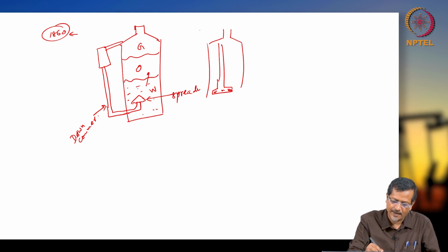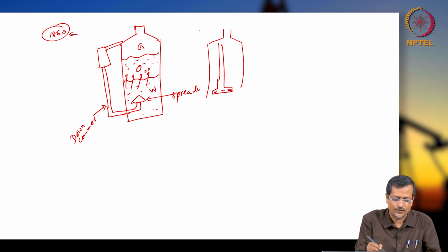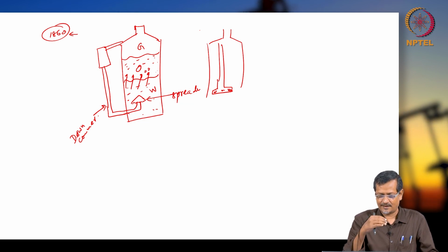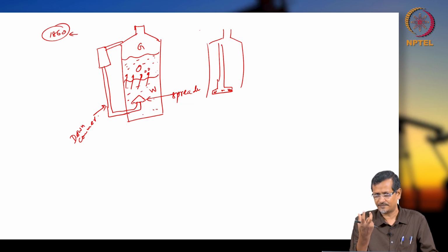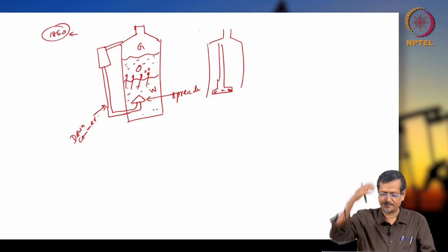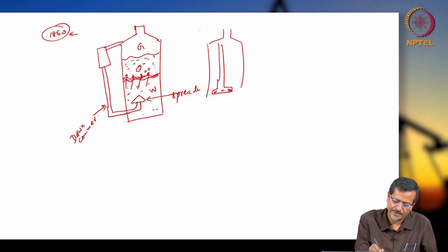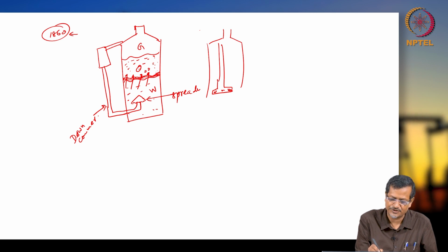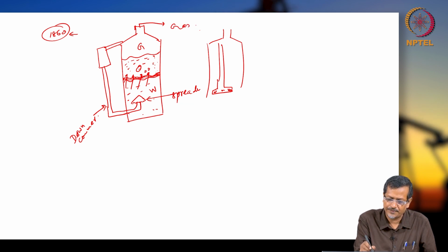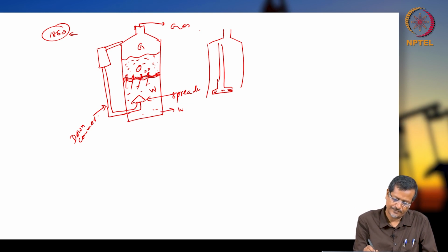So, whenever oil is moving up, oil particles moving up and creating an oil layer, okay. So, oil particles will be washed by water, okay. When water particles create bigger bubbles and they stay there, the small oil particles are washed and move up slowly, okay. And you are creating one oil layer, and there may be some emulsification zone, emulsion zone, okay. And this is gas. So, gas you can take from the top, definitely this is lighter weight. So, you have to take it from the top, and water you have to take from the bottom somewhere, okay.